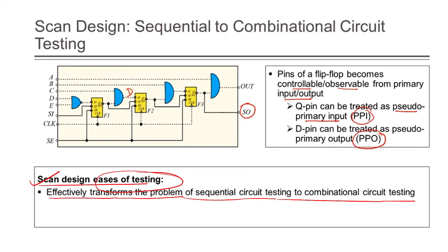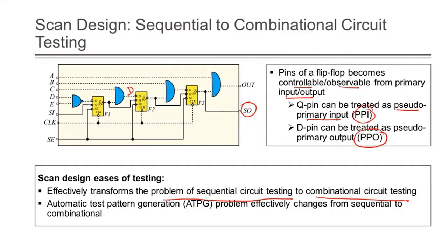We can easily give the test cases and identify where the faults, like stuck-at faults, are. That is the main advantage of scan design.